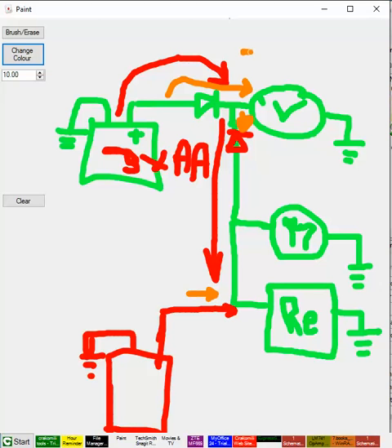And the clock, of course, is connected. Once it was connected to 220 volts and a transformer. Now it's connected directly to the rails. So this gives me a nice backup to the clock only, and the battery can stay with a leakage current of, I think, less than 1 microampere, so it can last, if not in use, for a few years.